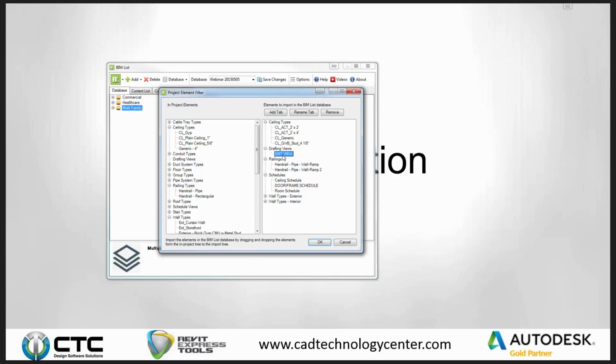So if I do add a drafting view over here, and then I go back to the original project and update that drafting view, how does this get that update? Well, there's two things I could possibly do. If I'm dragging it into a brand new project, it actually loads the latest iteration of this drafting view or any of the types automatically whenever I'm dragging it into a brand new file that's never seen it before. In the case of types, actual family types down here, for example, these different wall types, I can reload this back into my project and have it redefine the wall potentially.